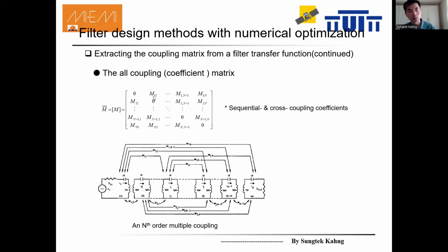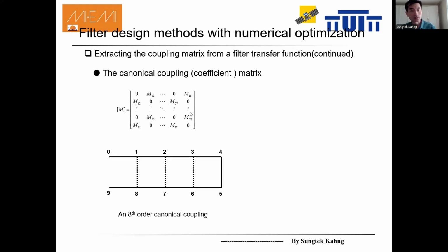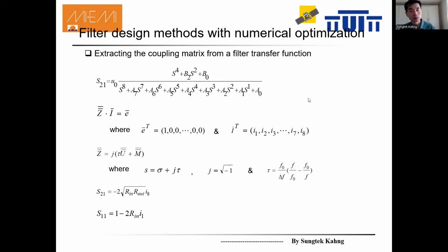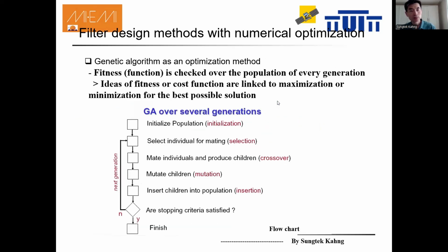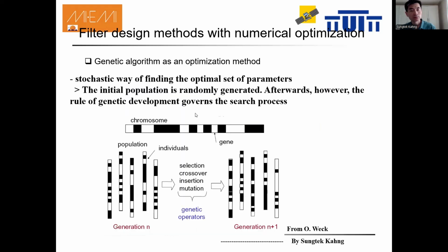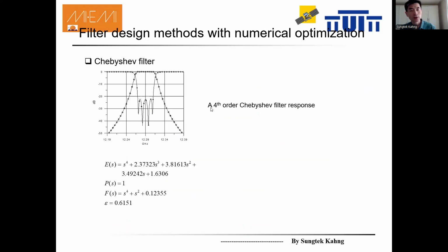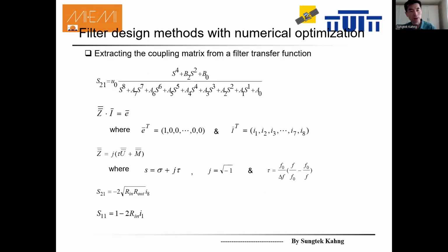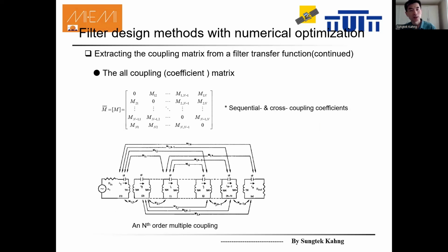Coupling coefficients directly tell you what values of coupling coefficients you need from resonator to resonator, from input to output port. So you can take one out of different approaches or perspectives. Configuration based like this, or the transfer function, which doesn't tell you the configuration explicitly, but inside you can get it. A coupling coefficient also tells you some kind of configuration very directly.